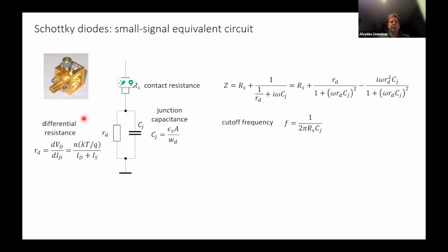Because a Schottky diode is a junction between metal and semiconductor, and once the carriers tunnel through the junction, the transport is in a region where they are majority carriers, so there is no loss due to diffusion capacitance. Still, junction capacitance is one of the most important. And in the electrical picture, it is nothing else than the shunting capacitance here.